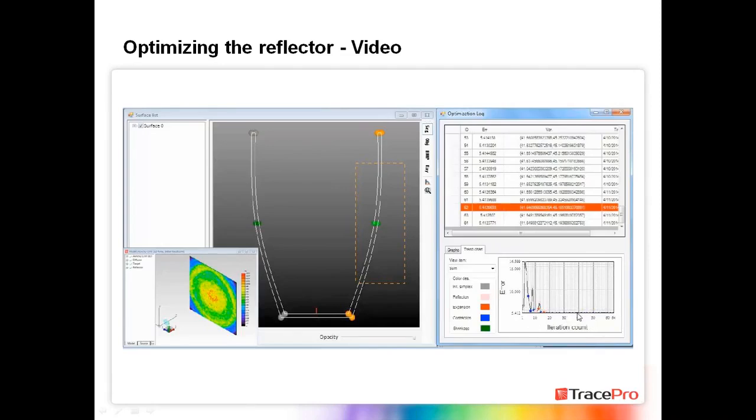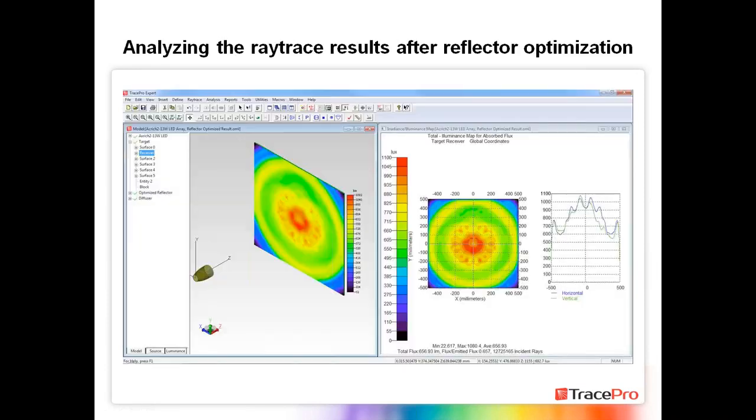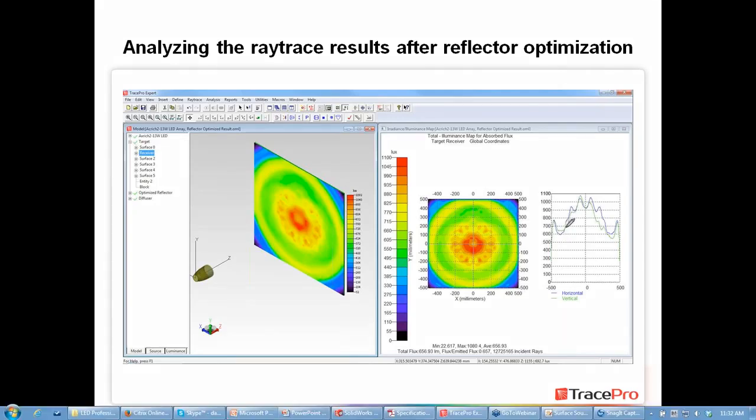The moves, the changes in position, are getting smaller and smaller. So it's finding a solution in this area. We can also see here in the trend chart that the values are staying about the same. They're not changing much. And in the optimizer you're able to set end conditions. How do you want to end it? By number of iterations, or by limits to how small a change is from one iteration to the next.